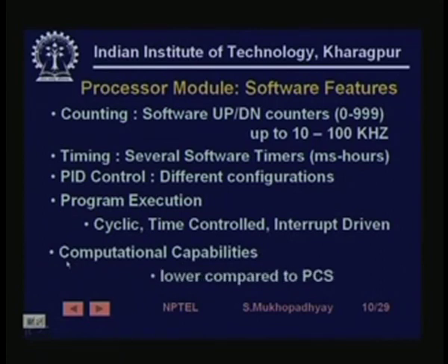But all said and done, one must understand that typically a PLC has much less computational capability compared to a PC, although it is generally much more expensive. Or that is, if you take PLCs and PCs of the same kind of price, then you would find that the PLC is much less computationally capable compared to a normal PC which sells in the market, both in terms of memory and in terms of computing speeds. That is because price of things get actually decided by the sales volume, plus the PLC has certain other features. They are actually very rugged, and they have a different kind of packaging.